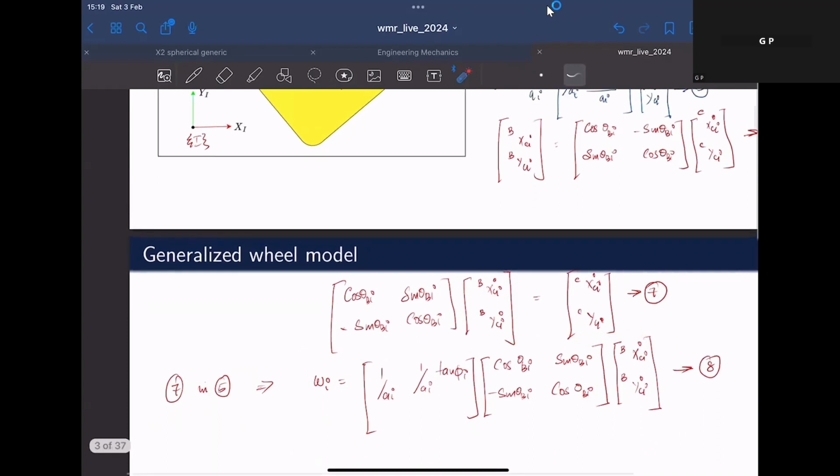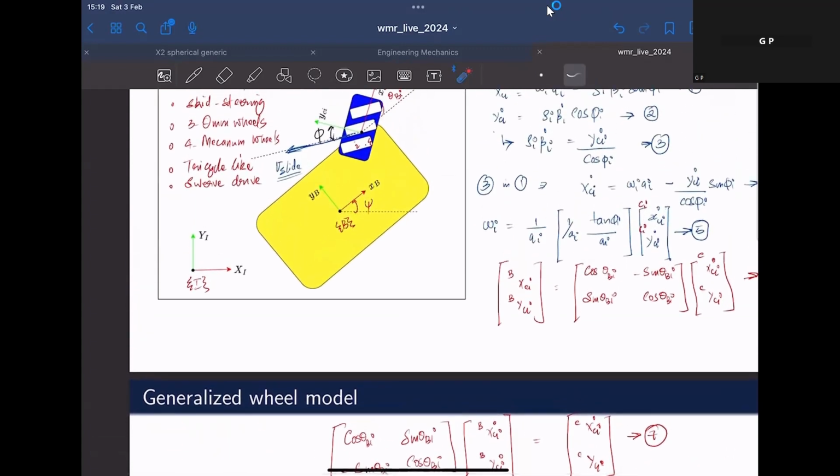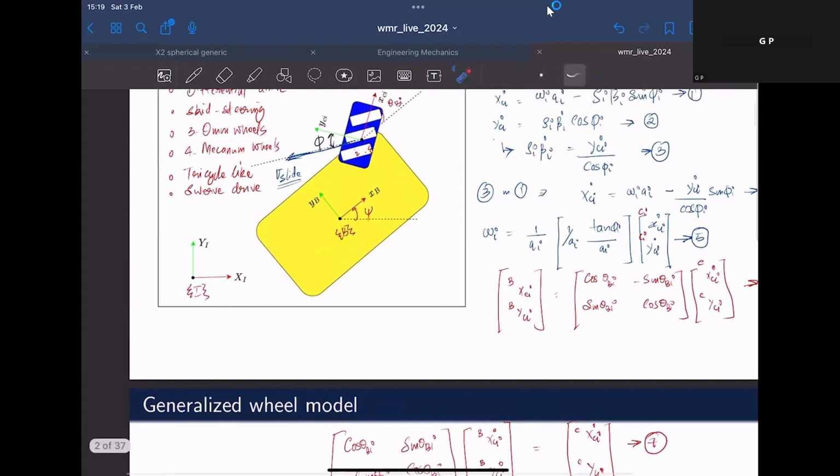And we also know that the velocity of the mobile robot will be mostly represented with respect to its local frame. If you recall the previous week's lectures, the notation we use for representing the instantaneous velocity of a mobile robot with its own frame of reference is u units per second along the xb axis, and along the yb axis it will be v.